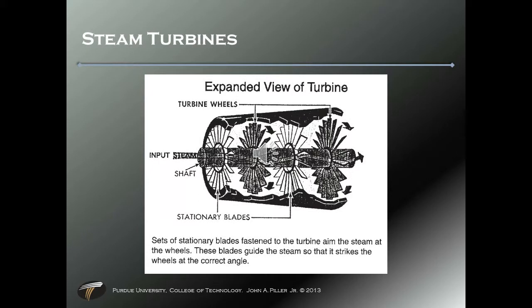We'll get to that. Power in the United States is mainly produced via steam turbines. 80% of U.S. power comes off of a steam turbine. We're not talking about how we get the steam, we're just talking about how we get rotation on the generator. Basically what happens is we force steam into this turbine. The rotary motion spins the generator. We refer to that as the prime mover. The steam is the prime mover that turns the turbine. Okay? This, like I said, is a reaction turbine.